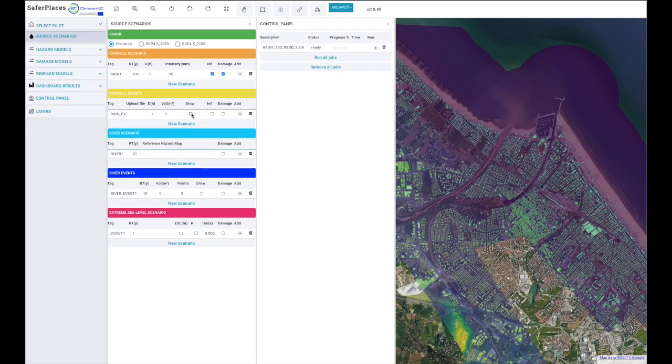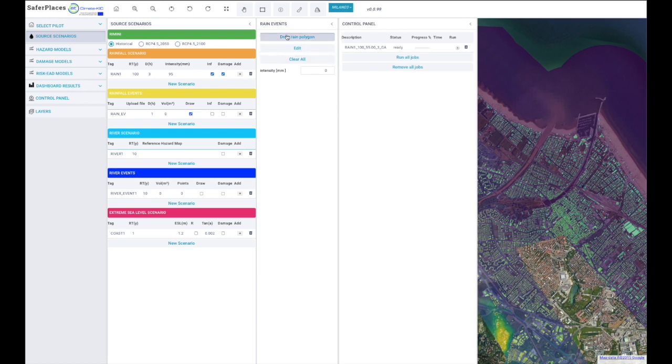The user can define multiple polygons of rainfall areas with tailored total amounts in millimeters. Gradually the number of polygons and total volume of rainfall is reported and updated in the scenario. In this case we have generated two rainfall spots of 90 and 60 mm for a total volume of less than 300,000 cubic meters. After a few seconds the user can display the flood hazard maps.